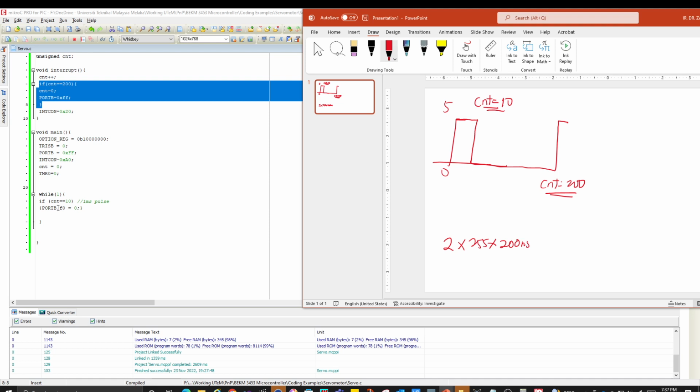For example, just now, one time here, this is only 10 times, right? You have to count, go here, back again. Every time the interrupt happens, it will go up here and then up to 10 times. Not only one interrupt happens, you calculate. This is only one interrupt. So right now you are checking up to count is equivalent to 10, so you must multiply by 10 over here. So that will be the time needed.